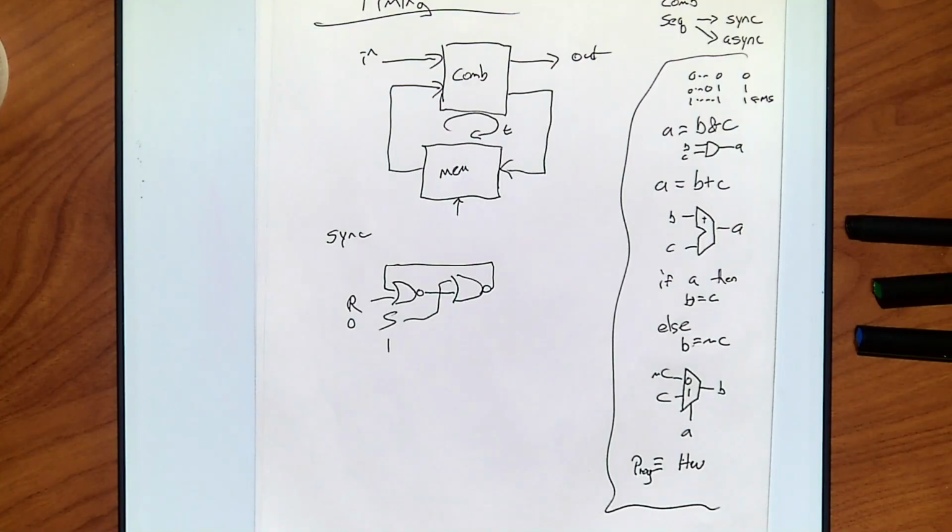And it's starting to get annoying. What if it gets to the middle and it gets stuck? Right? Because I turned it off partway. Now it's become metastable. And you don't know when that dumb thing's coming off. See what I'm saying? There's a lot of things. Even though I'm avoiding the whole 1-1 problem in disconnecting, I can hit metastable by not giving stable inputs, right? If I'm just going like crazy, flipping things, I can do all kinds of weird stuff, who knows. You just always have to be careful.